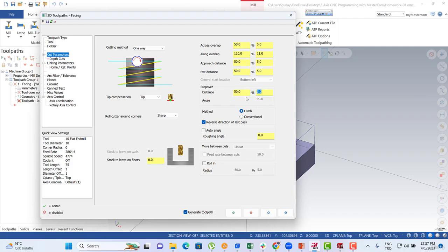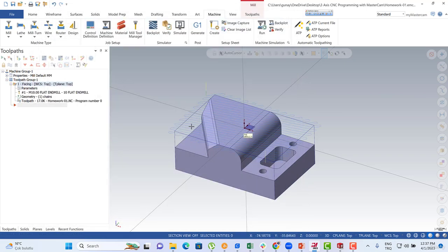It's 5 millimeters, and then we can turn to our roughing angle here. We can also prefer to use the high speed toolpath for the zigzag method, and then activate the high speed loops, and that's it. We just need to hit the OK button.